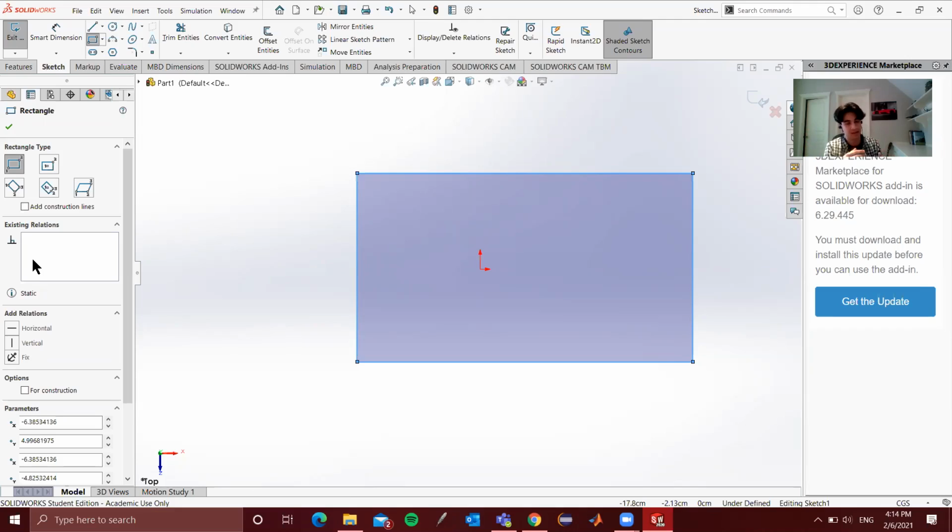So that's not good. In most mechanical design projects, you want your sketches and your models to be fully constrained, such that if some other person on your team changes something, your whole model updates accordingly, and it sort of adapts to the new change. We can do that with multiple tools, which we'll see further ahead.